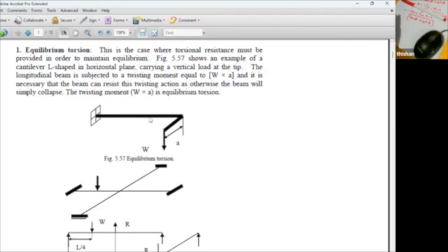Make sure we have closed links. And I showed the shape of the link, the closed link, and you must provide that type of links. And when you do the calculation, what is the result? If the torsional moments are high, what would be the diameter of the link? You can easily get 25 millimeter links or 20 millimeter links at 100 millimeter centers.